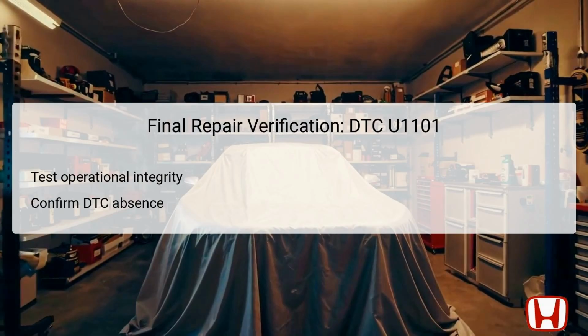It's critical to look for any recurrence of the DTC as well, utilizing the HDS once more to confirm no lingering codes will provide reassurance that the earlier communication issues are fully resolved. The integrity of connections and components must be ensured to avoid future operational disruptions. Following this repair verification process will help to validate the success of the troubleshooting efforts undertaken.